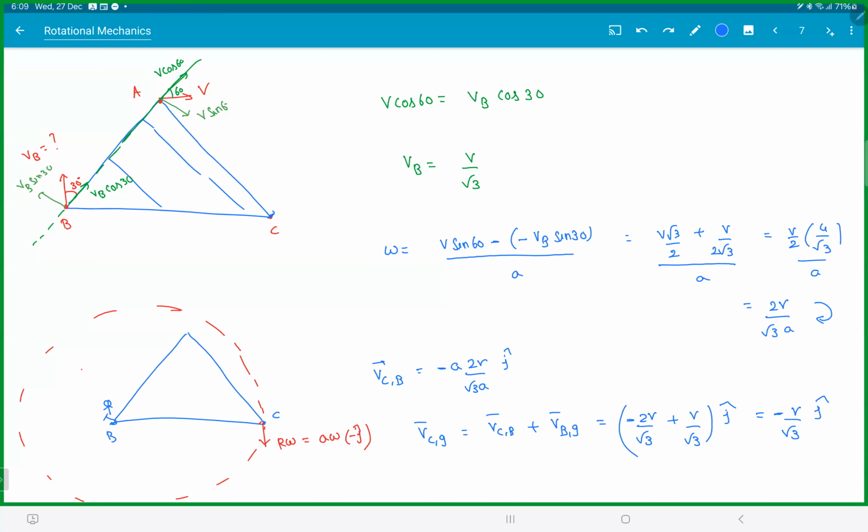Check it out. I can ask you find the velocity of centroid also. Now I can ask you any point. But I hope everyone is getting the idea here. You know how to find omega. Once you get omega, just stand on some point whose velocity you already know and just look at any other point. It will go in a circle and then just add it back. Clear with this?